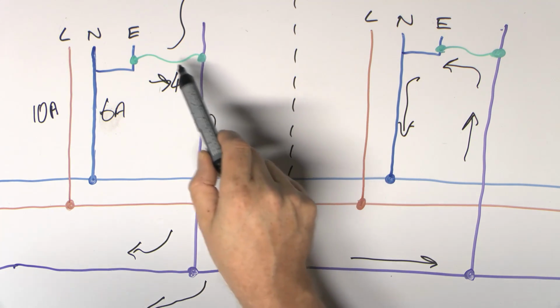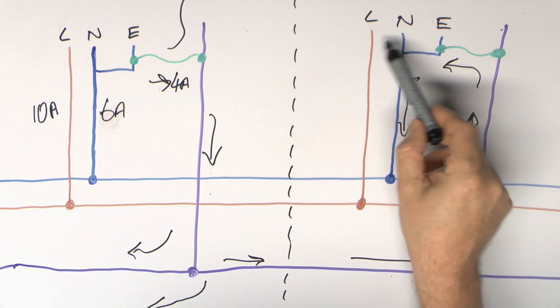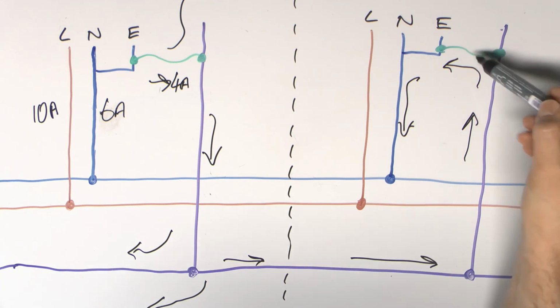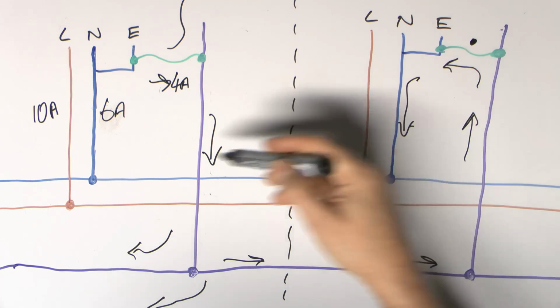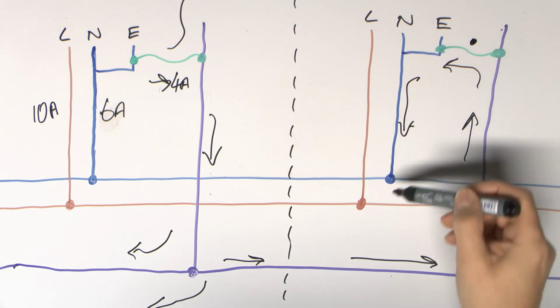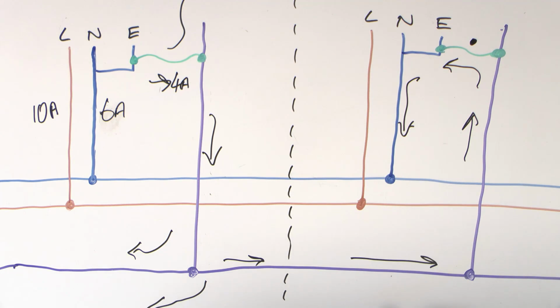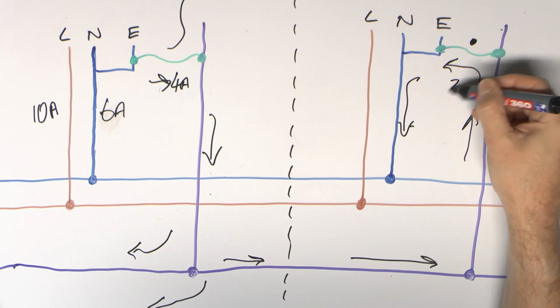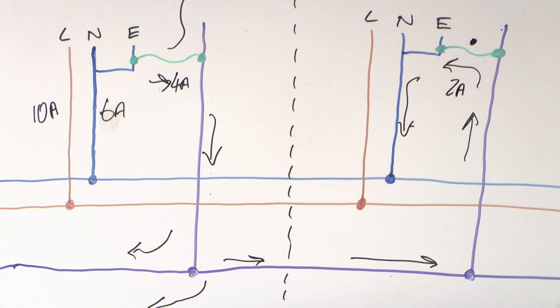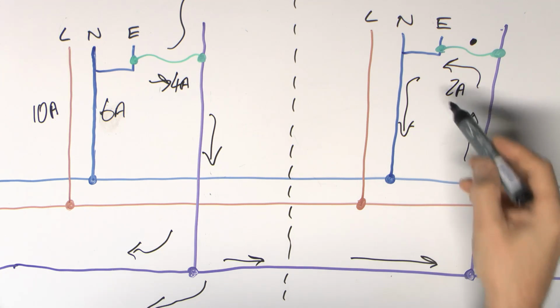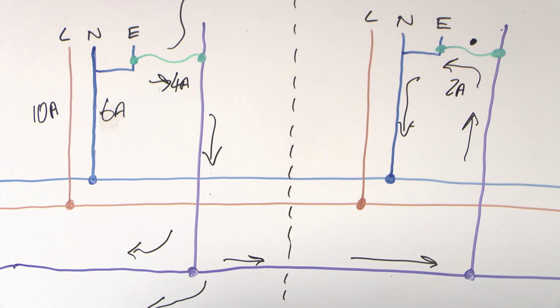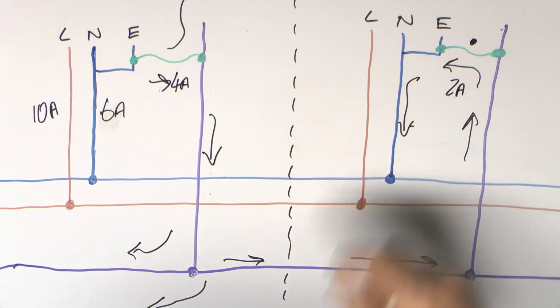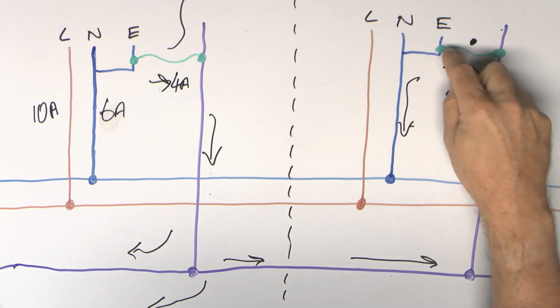However, there may be current here because if you go to next door, let's say that their supply is actually turned off for whatever reason, you might still see some current here because it's coming from next door, just simply going around there into the combined neutral and earth conductor and back into the supply. It could be, say, the full 4 amps there, it could be, say, sort of 2 amps or something. But again, this is quite normal. Bearing in mind we've only got 2 properties here, you could have a whole row of houses, say 20 of them, multiply this up by 20 with various loads on each one, you will be seeing some current in these bonding conductors. However, the important thing here is that if you were to disconnect this here after isolating your supply,